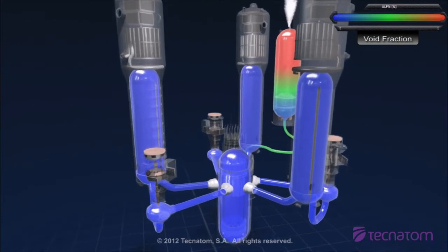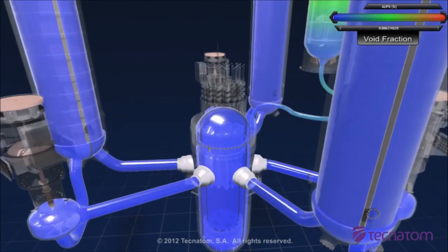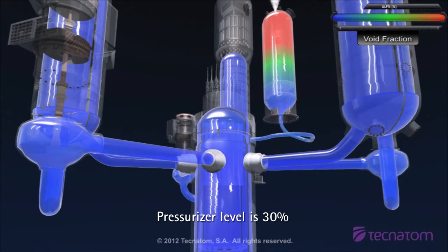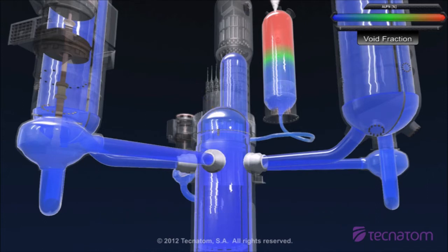Let's have a look at the void fraction of the primary. Right now, primary system is completely filled with subcooled water. However, temperature is increasing due to the low level in the steam generators, and the pressure is dropping rapidly as pressurizer relief valve has failed open. Steam will be formed very soon.